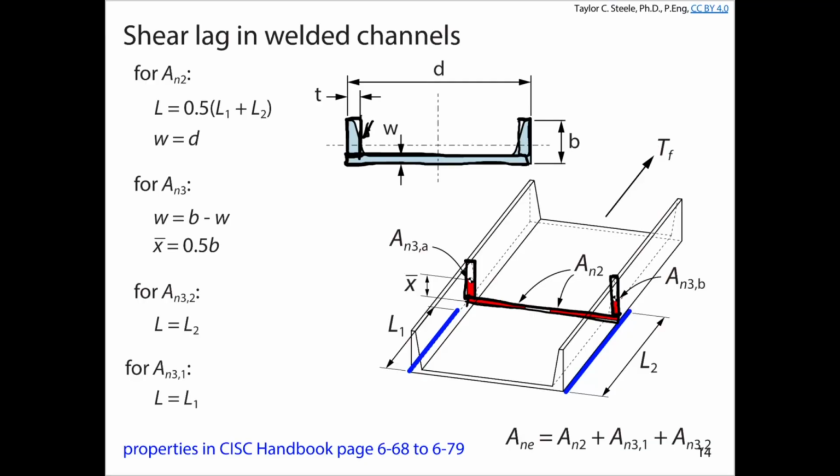Well, not so long ago, we looked at what happened if we had to account for offset in the bolts. We had staggered bolts potentially that we might need to consider. If we have welds like this, the fracture plane is actually going to fail something like this, and it's going to be on a bit of a stagger, something like this. And so in this case, it's very minor. It's probably not going to add a significant amount of area to your net section,